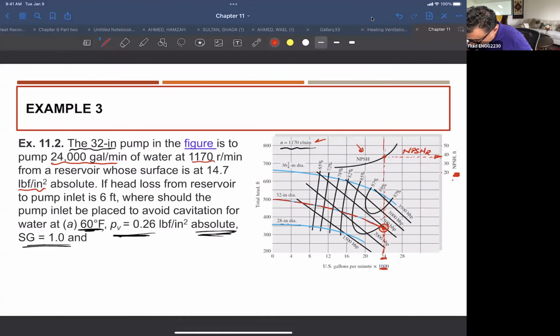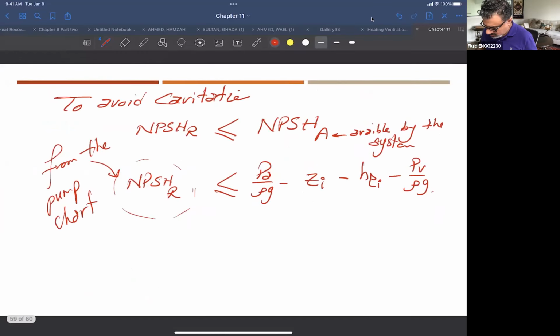So you see the flow rate Q, and then you find the value on this curve here. This is a manufacturer condition that depends on the design of the impeller, how the impeller looks, and this value is manufacturer-provided information. It is not a function of something else. This is a design-given value, and it is much more complex than the system part here. So this is provided by the manufacturer.